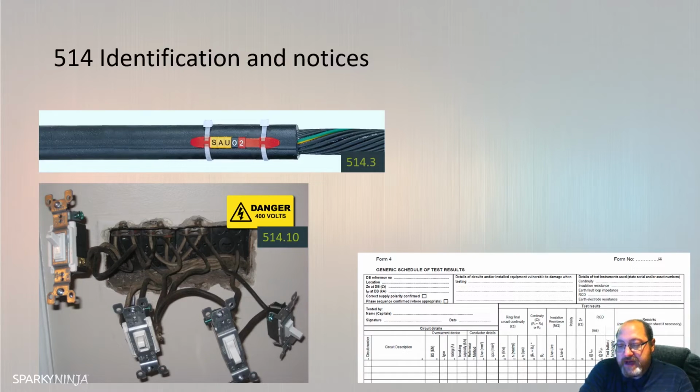The identification shall be given in letters and or Arabic numerals. In order to avoid confusion, unattached numerals 6 and 9 will be underlined. So if you have an unattached 9 or a 6, there must be a line underneath it to show which one it is. Protective conductor: green and yellow identification shall not be numbered other than for purpose of circuit identification. With alphanumeric and numeric numbering, the number 0 is reserved for neutral or midpoint. And then you have some omissions.